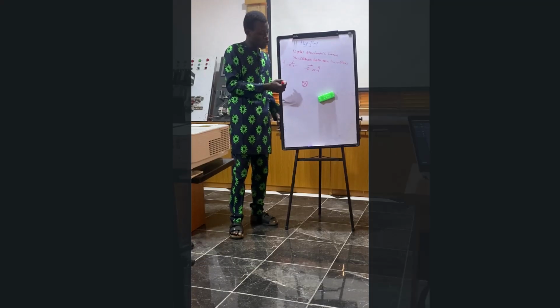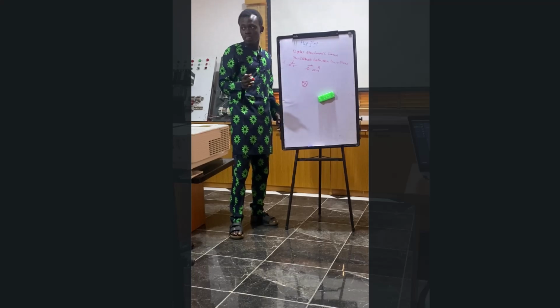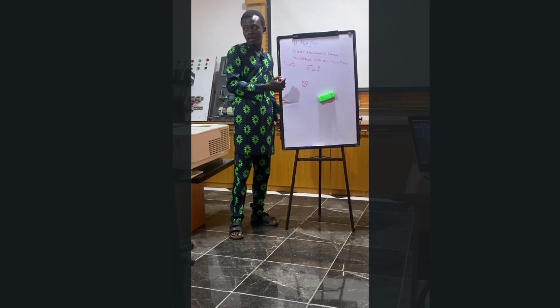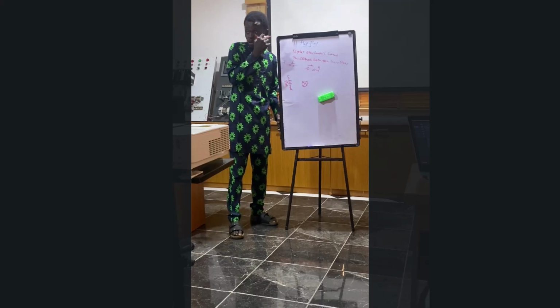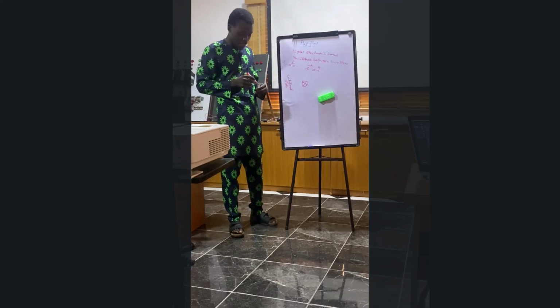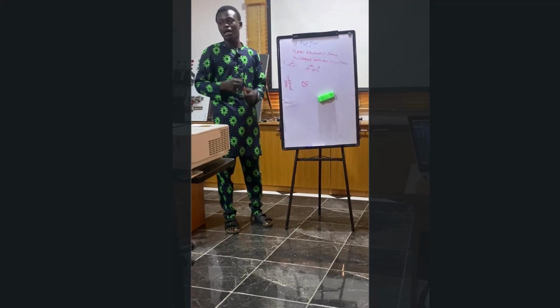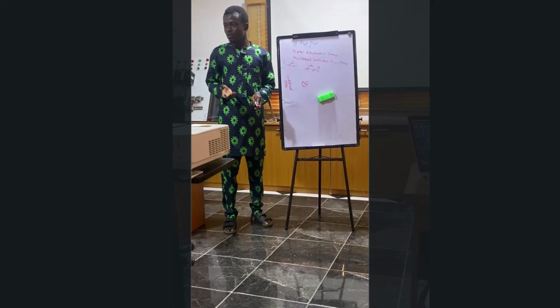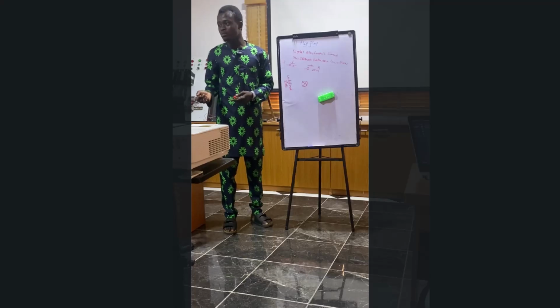Okay. So in theory, when you press the two at the same time, what you're supposed to have is an undefined state. So it is such that when you press the set button, the lamp should come on and remain on until you press the reset button.